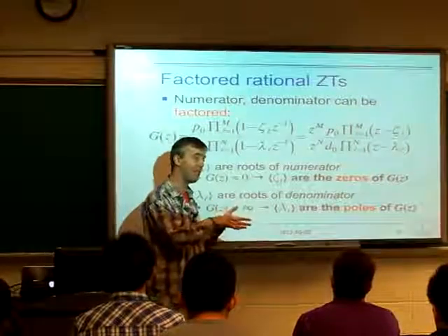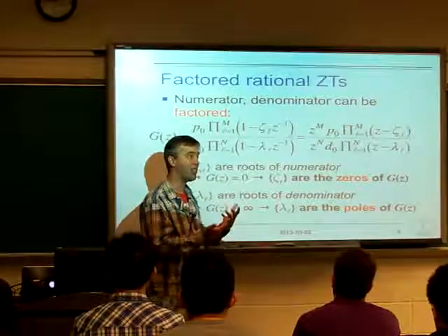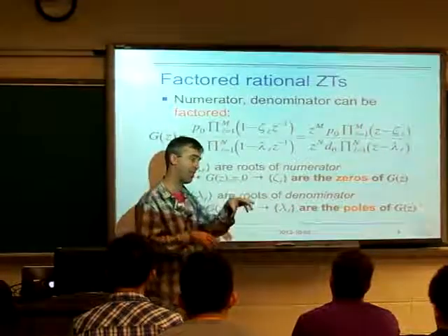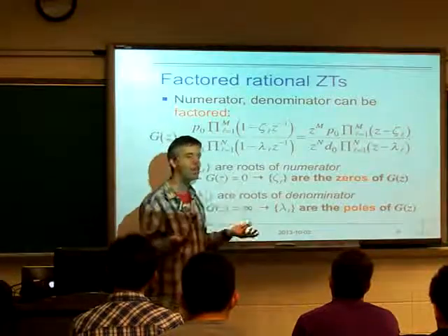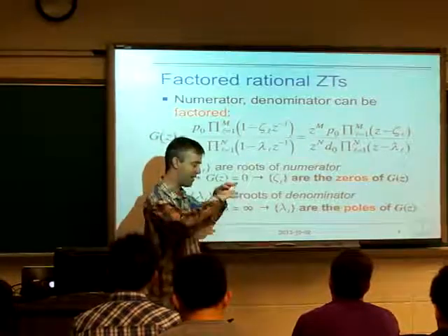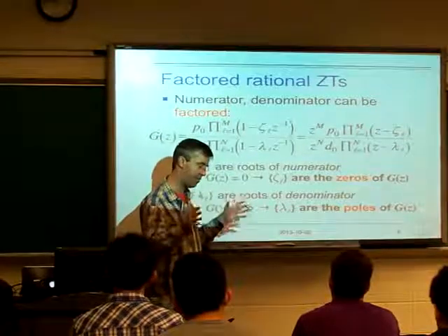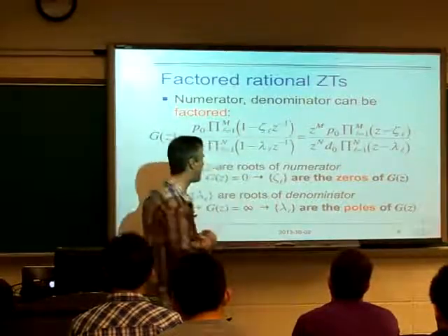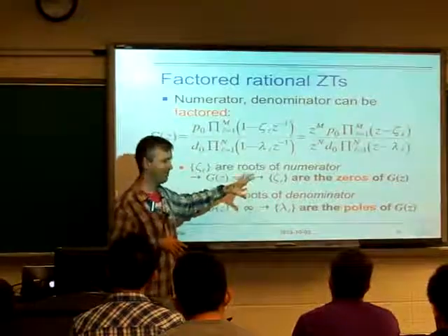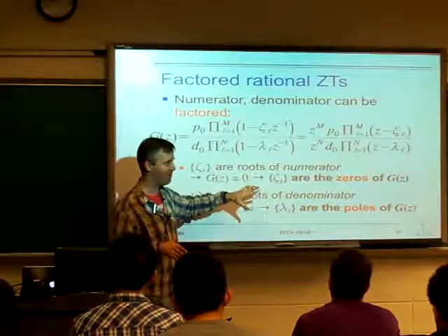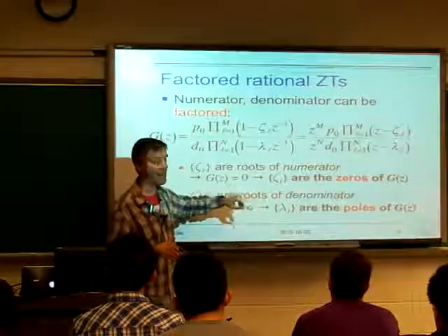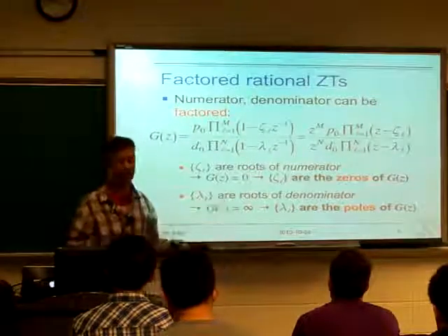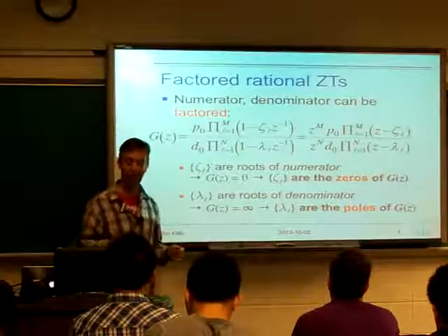It may be that the poles and zeros aren't in the region of convergence, aren't actually values of Z where this closed form expression matches our Z transform, but they still determine its behavior. Now all we care about is the overall shape of this closed form expression, which is determined by all the poles and zeros, even if they're not in the immediate vicinity. And this is how we end up forgetting about the region of convergence, because now we're just interested in this closed form expression, and it's easier to think about those over their entire surface.